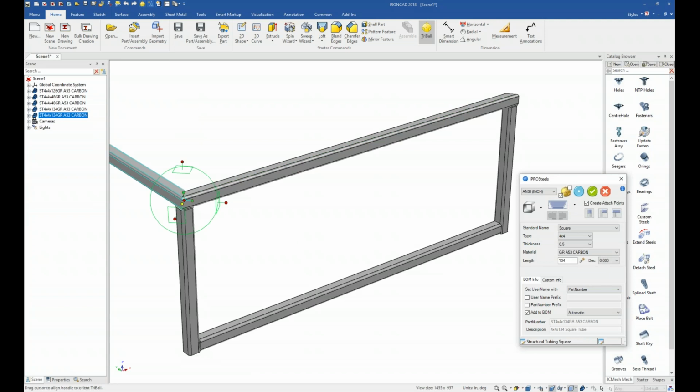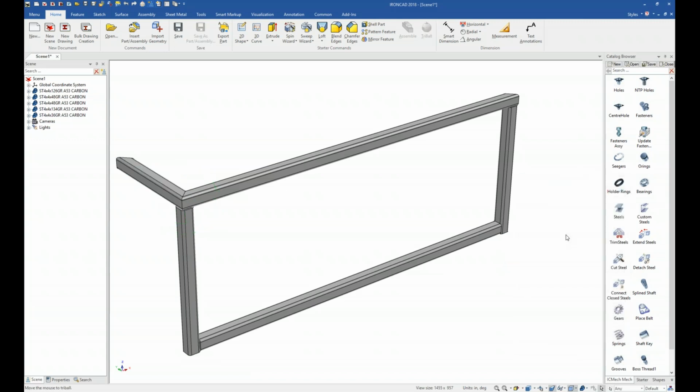It knew there was an angle 45 there, so the new tube that gets dropped automatically has that versus being a square section. So a little bit more added intelligence there. And we just give it a certain length inside of this, 36. If we hit apply, we can see our angle on the other end is pointing the wrong way. So we can go back into our angles and change our start section, our end section to 90. Hit apply, and we can see, okay, now it's actually cutting the right direction that we want,